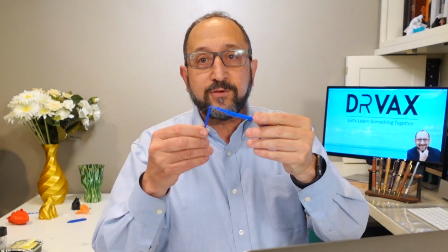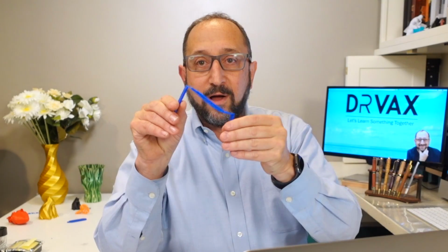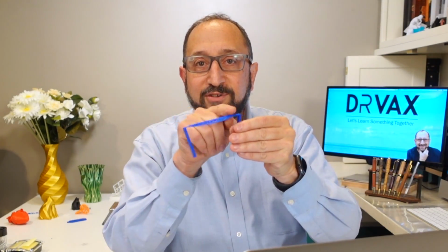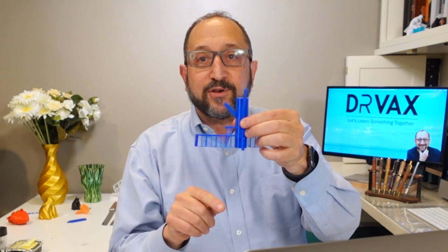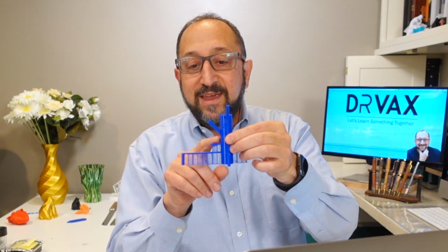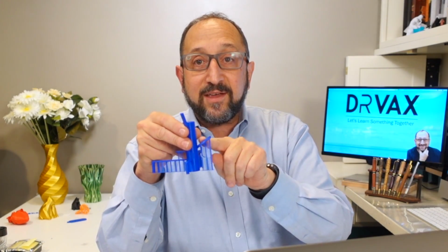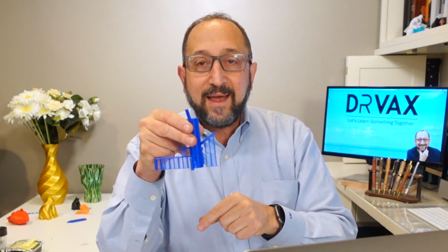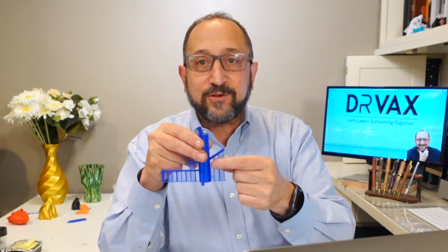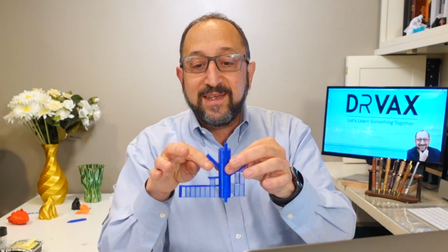Well, 3D printers have no trouble printing things that are vertical. These walls printed fine on this model. It was the horizontal surface that was a problem. And it's not all horizontal surfaces. You'll see that these, even this structure, has a support structure under it, whereas these two do not.